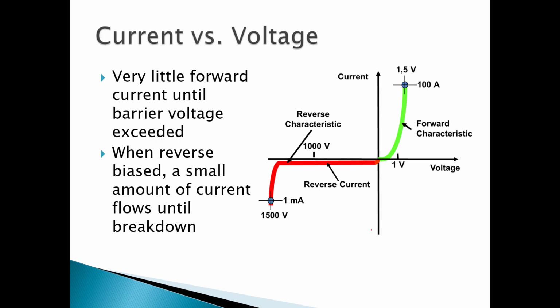So this was that curve. You've seen something like this, several times. Here's that 7/10 of a volt here, right? That little voltage, which once I pass it, it turns on. And so we often think of the diode as being, it does nothing, and then it turns on.